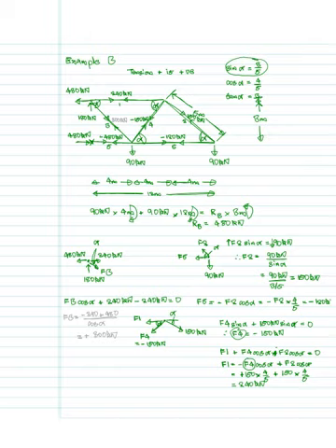And then from there you get F3 is equal to negative 240 plus 480 divided by cosine alpha, and that value, when you calculate it, comes out to be positive 300 kilonewtons, which obviously means tension, and so we'll write 300 kilonewtons there.